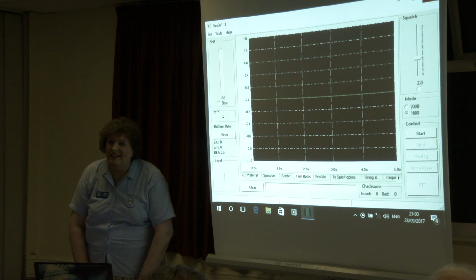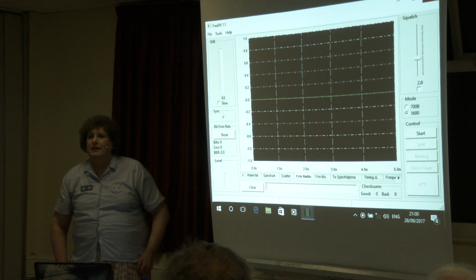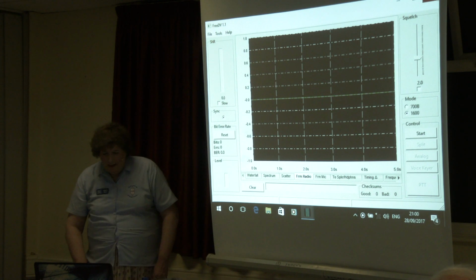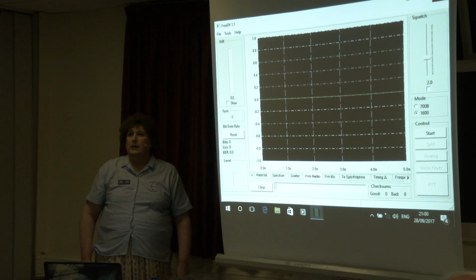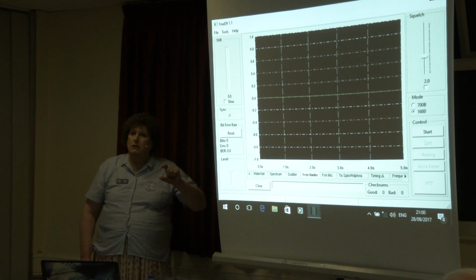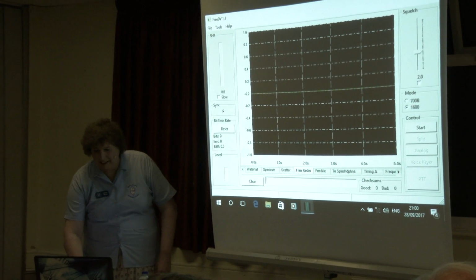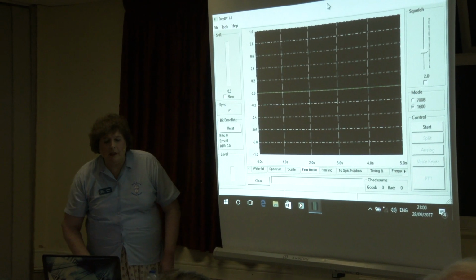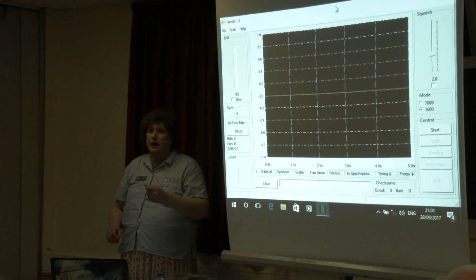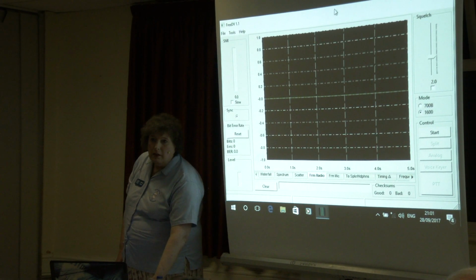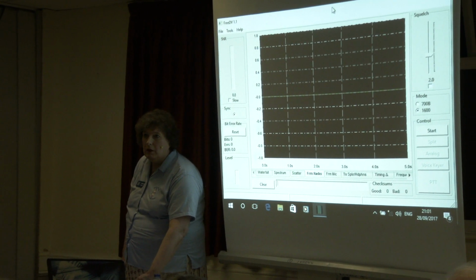This is quite embarrassing when you're listening to a data mode segment and somebody is driving in from their main sound card and you hear the usual Windows operating system noises, because they've mistyped a key or something. Well, that's one of the beauties of using USB sound card adapters. You don't get that noise. Don't set it as your default audio output, so it doesn't get handled by the Windows settings, because a lot of the operating noise you hear in those modes is where people have used the straight line input or audio output direct on either the PC or laptop.